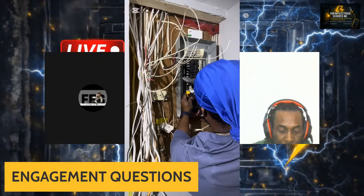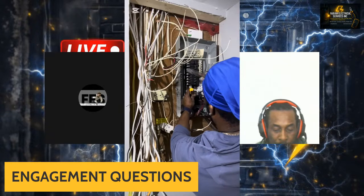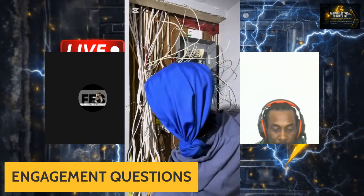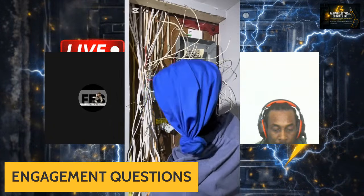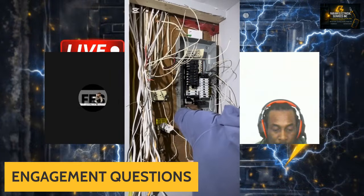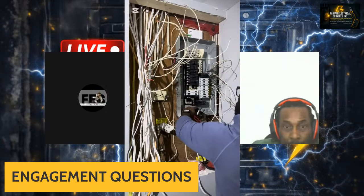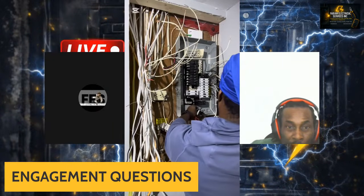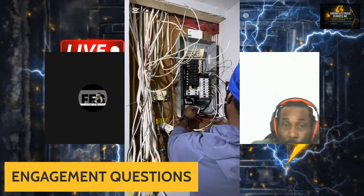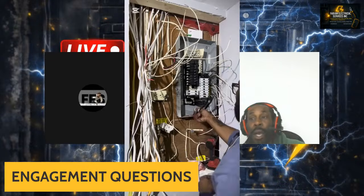So again, hello and welcome back to the channel. So normally what I do when I'm doing a job like this is I get to the job site a little bit earlier so I can remove all of my wires and label them accordingly. That way, when it comes to reinstalling my wires into the panel, I don't have to go troubleshooting throughout the house for the circuits to be labeled. And yes, of course, your cables and your circuits have to be labeled at the end of the job in order to have your inspection pass.